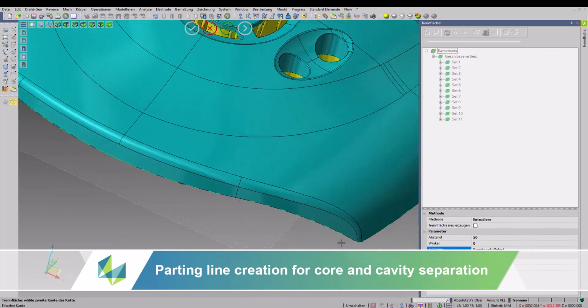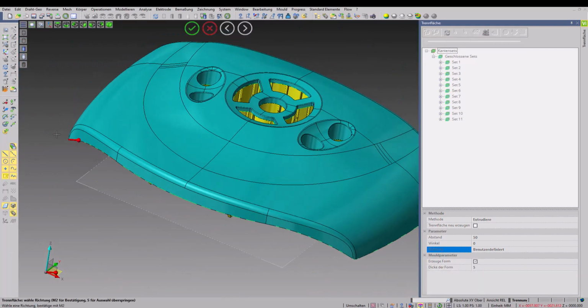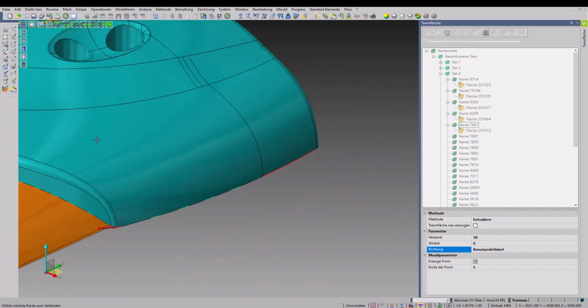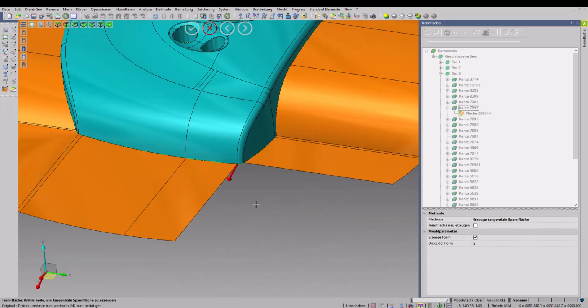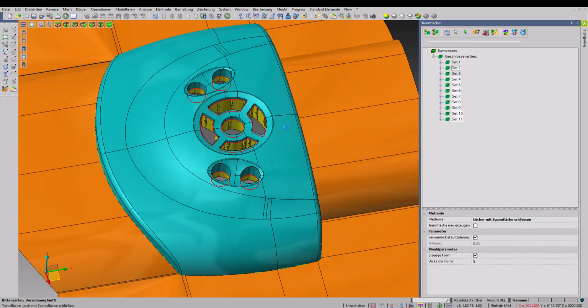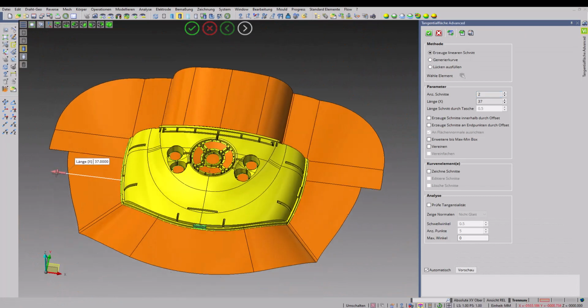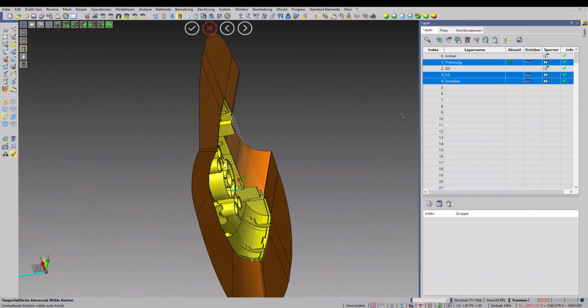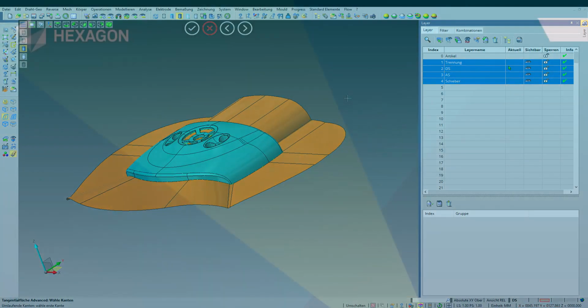With the split line defined, you can now quickly develop the parting surfaces using various techniques to divide the solid mold base into the core and cavity. These surfaces will be used later to shape the plates in the mold assembly.